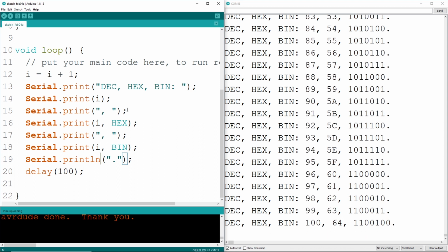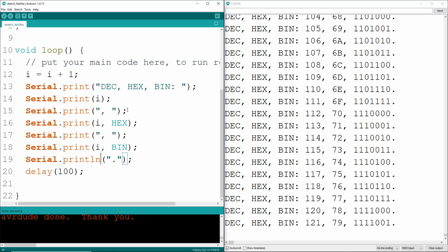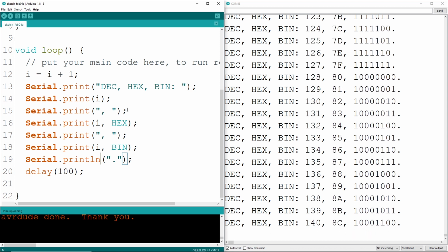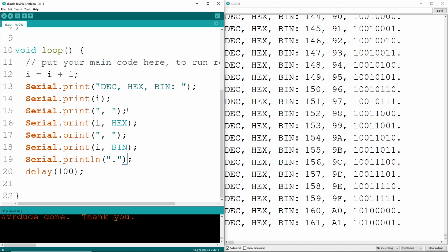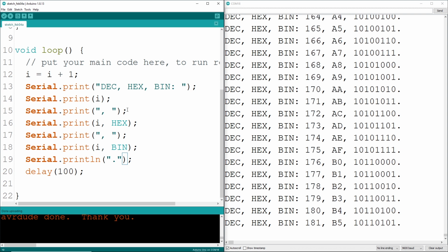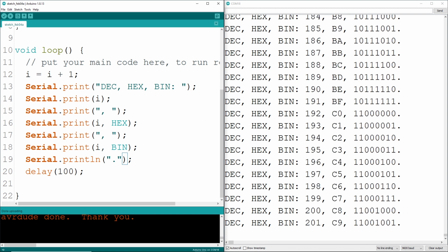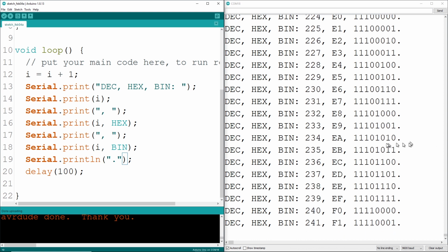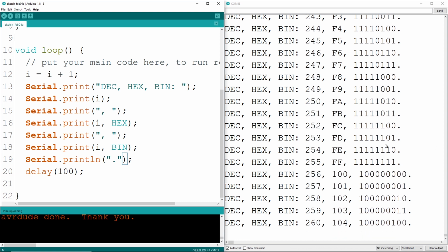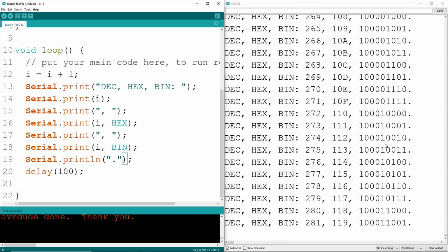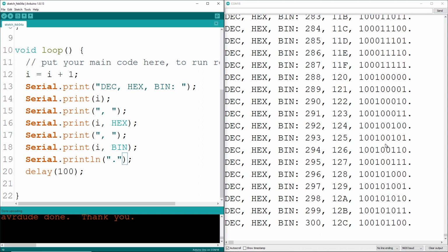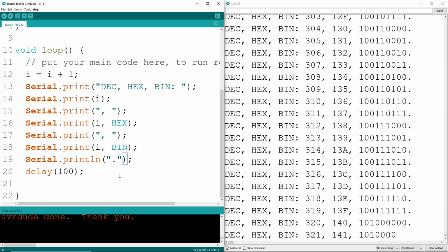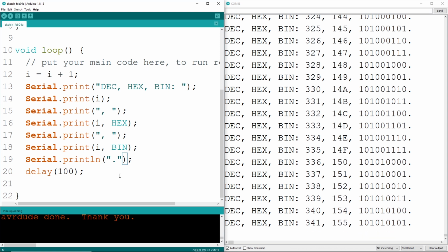So far, we've been dumping data to the serial monitor, but you can input data to tell your Arduino to do stuff. This practice isn't real common, and since I'm trying to keep these tutorials short, I'll cover that in the future. As you try things on your own, here are some tips if serial monitoring isn't working. Make sure Serial.begin is in your setup section, and make sure the baud rates match. You can write more than one variable to the screen, but I'll save that for the next time, where we'll learn how to measure analog sensors.